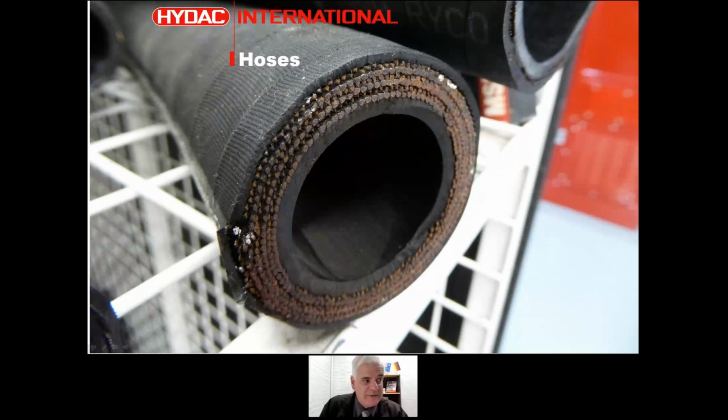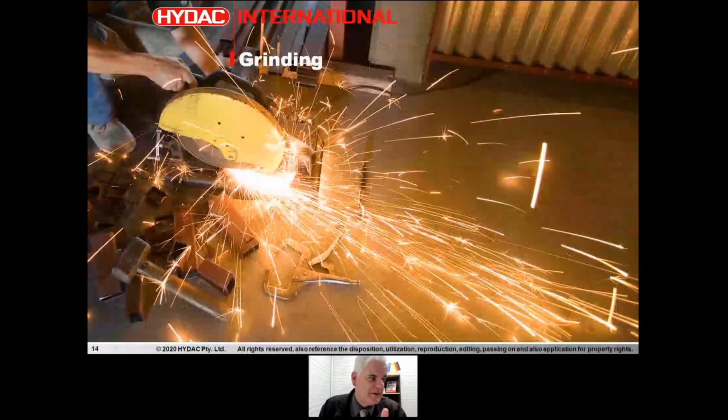And also, particularly these larger spiral type assemblies, if they're going to be cut using a drop saw, which is like a grinding disc, then we also have abrasives from the grinding disc also going to be deposited within the hose. So it's absolutely critical that as we're assembling that system, as we're assembling that hose, we have to absolutely clear that out, because those contaminants are very damaging.